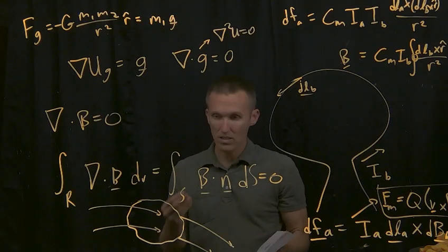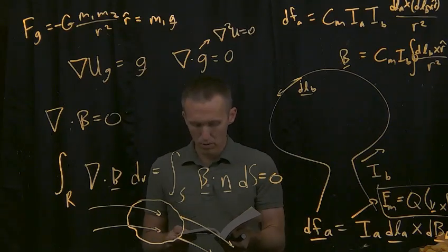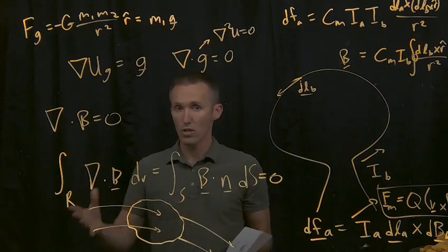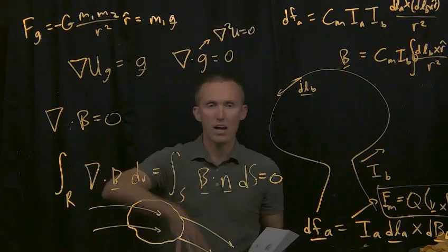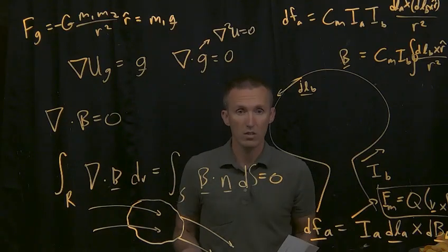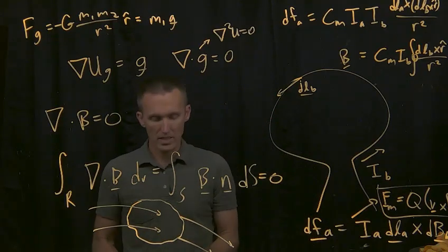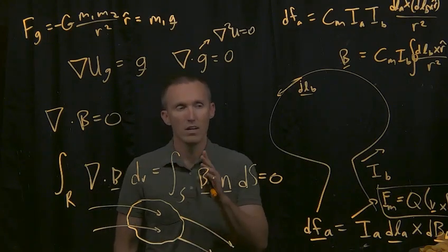What this also means is that if you are able to measure the vertical component of the magnetic field over a large enough area, all the ups and downs of the field should eventually smooth out. You should get an average field of 0 if you're doing a magnetic survey. So this is actually very useful for geophysical surveys.